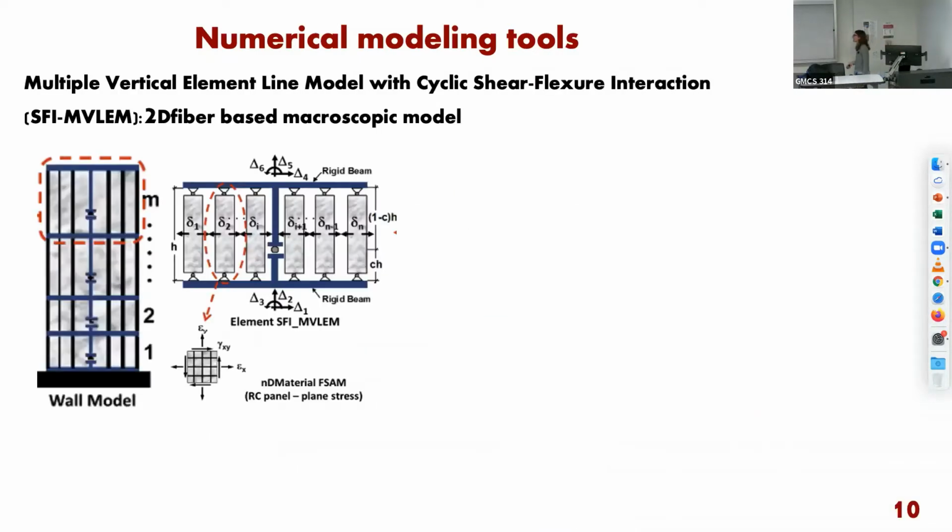And so there are many models within OpenSees you can use. You can select your own model. You can also build your own model. I used a 2D fiber-based model that was developed by Professor Kolozvari. It's called the multiple vertical element line model, and it's able to capture also the shear-flexure interaction behavior of the